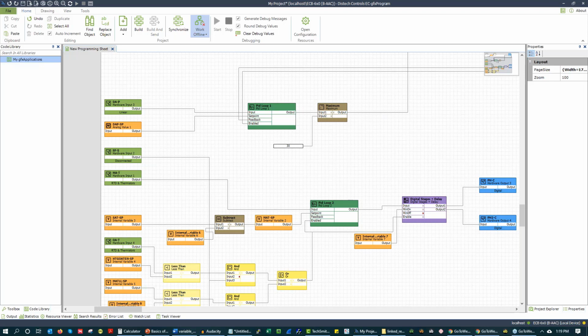All right, how many programs will typically exist in a BAS? Do you create programs for each controller and for each utility system? Typically, programs will exist based on their uniqueness. Let's say you have a cooling-only VAV box, a VAV box with reheat, and a series fan-powered VAV box. You may create three programs, and then download that program to each VAV controller based on its type. You typically create a program based on its type, and then you modify the settings in the software.